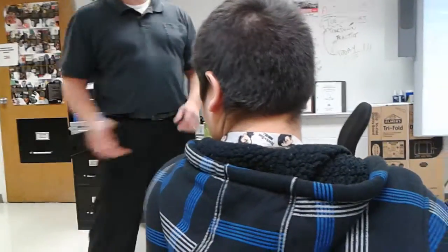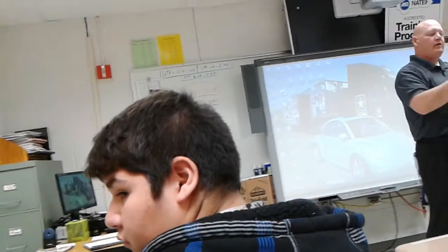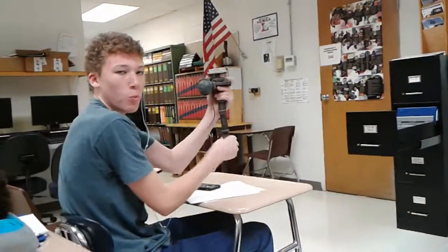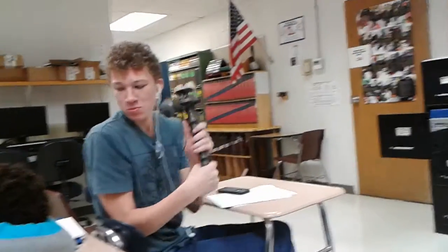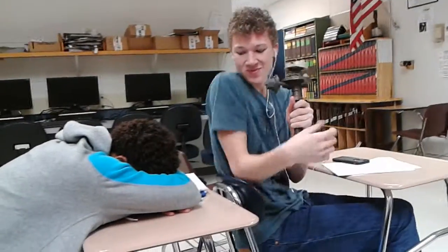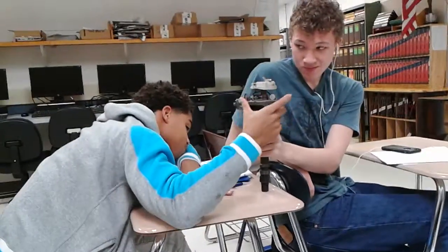When they're closed, the electricity is flowing through this coil, building up the primary. When that comes over here, I want you to hold it. Okay? When these things break open, that's why a lot of people call them breaker points. When the circuit is broken, then the magnetic field collapses. That's when you get the big spark. Okay? So,